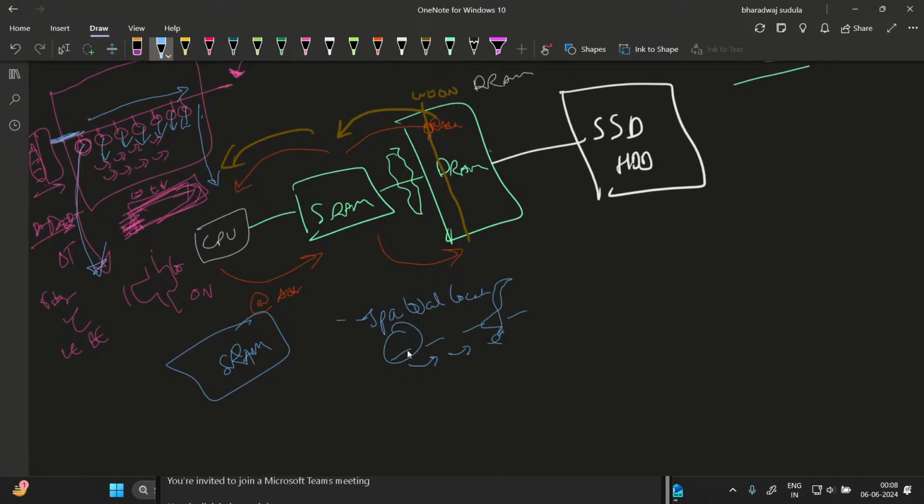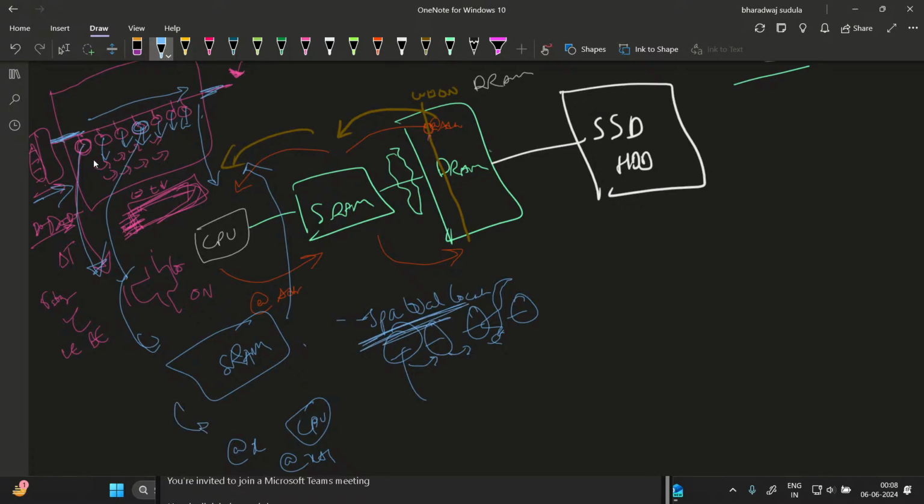So if we take the entire row, it might come in handy in future. If the CPU asks for the next address, let's say previously you accessed X, now you need X plus 1, then you would need to go to DRAM again, row decode, select the word line, select the cell and get the data again. Instead of doing this again and again, you exploit spatial locality and bring the entire row. Thus you have the entire row data in SRAM and you can access it easily.